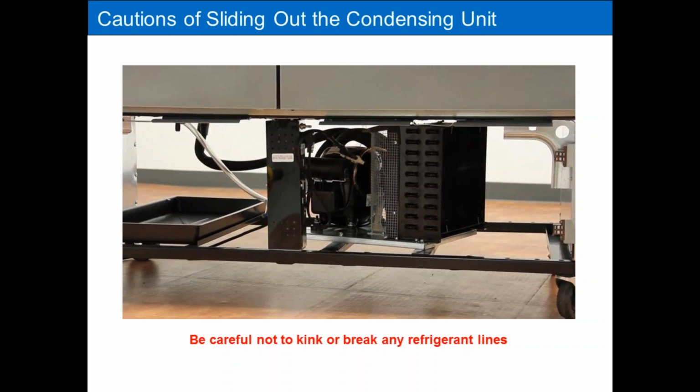I heard that magic hissing sound that you never want to hear as you're pushing it back, and I had to take it out, repair the suction line, re-evacuate the system, recharge it. All extra time and materials that was my error, and I could not charge the customer.